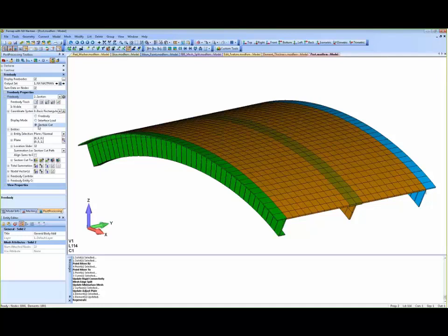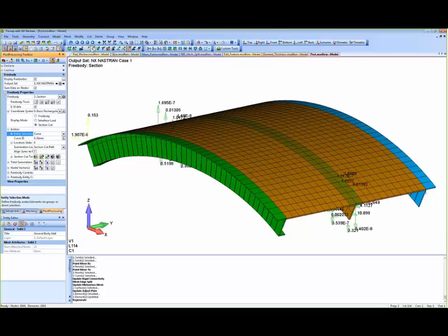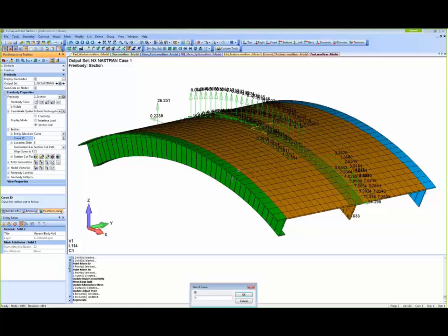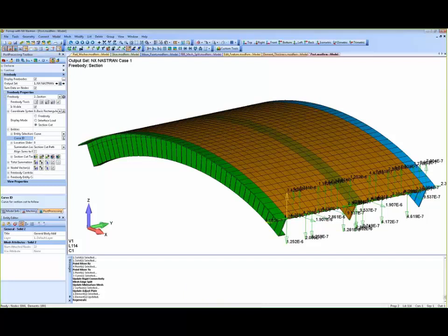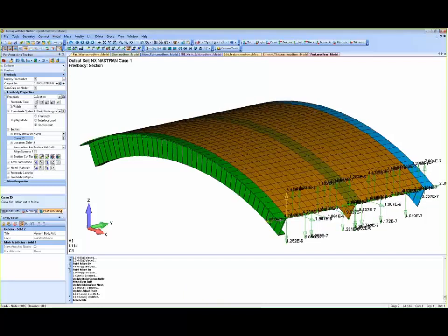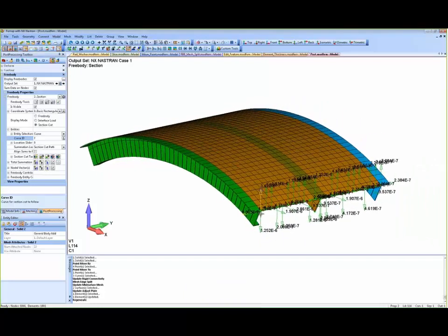So some of the options we have when we hit section cut, I'm going to select it not using a plane, but I am going to select a curve here. It automatically defaults to selecting a curve. However, I'm going to change it. I want to select curve right here, this curve 7. Now by doing that, it defaults to putting the summation right on that curve.